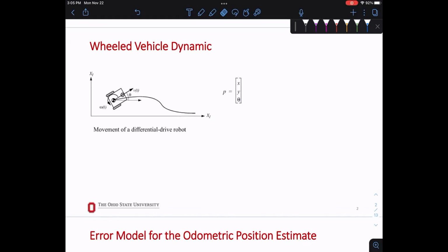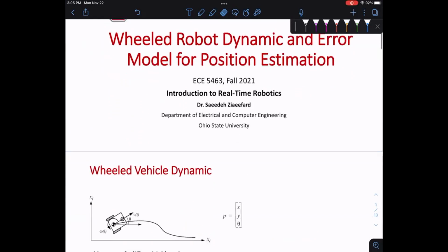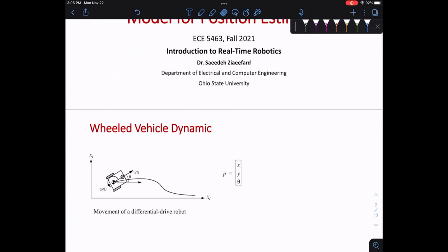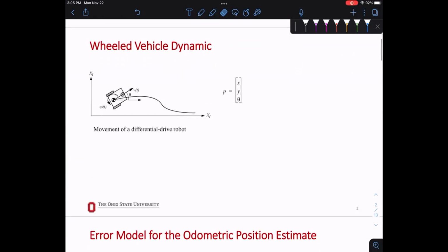All right. So for today, I chose wheeled robot dynamics, which is independent of what we had so far, and I think this was a good opportunity to fill this in. If you remember from our very early discussions about degrees of freedom, we said that if a mobile robot is not moving in the Z direction, ignoring the suspension that has minimal Z elevation change, you're only going in X and Y and turning, so it has a theta. So we can give it 3 degrees of freedom on a plane.